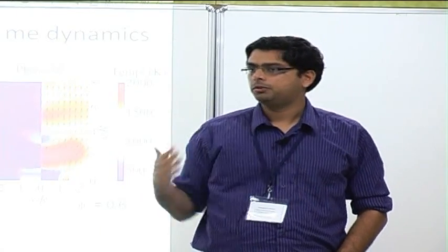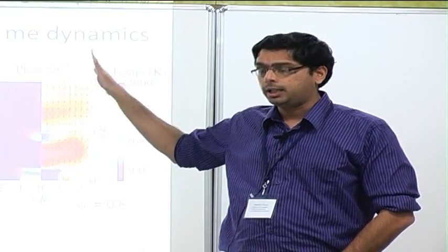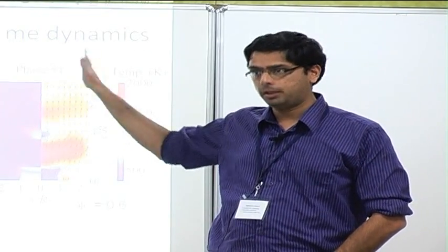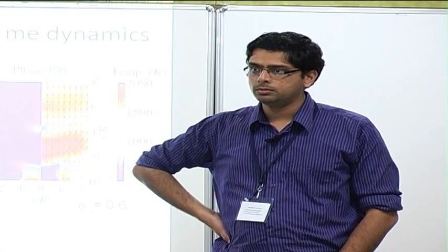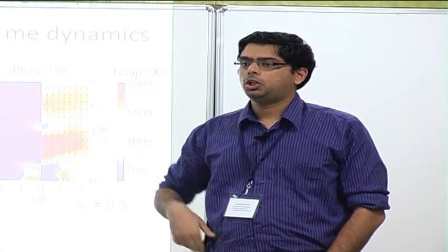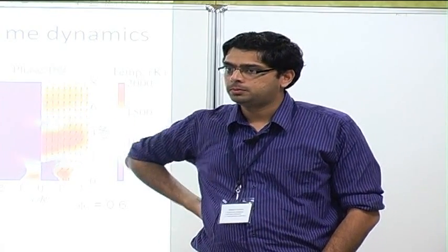Yeah, SL versus phi. Which correlation I get from an analysis, and SL will be a function of equivalence ratio, right? Sure, absolutely. I was thinking you were getting the burning velocity from the heat release itself. No, generally not in the reduced order model. In the DNS, of course, it comes from whatever chemistry I assume. But are you using DNS with full kinetics? Yeah.